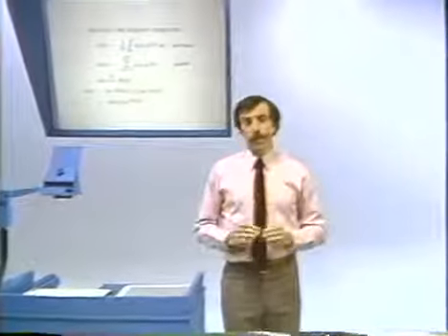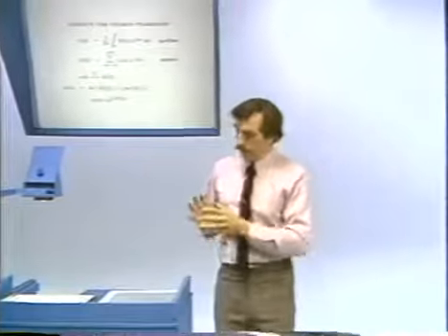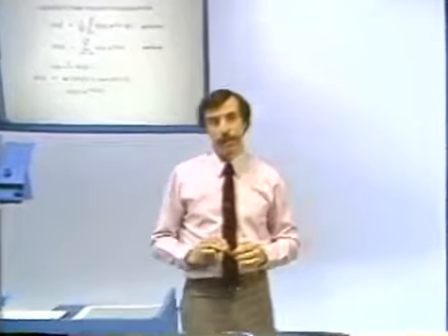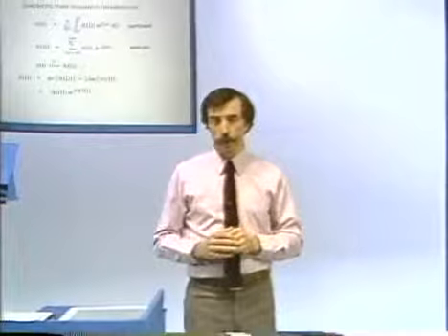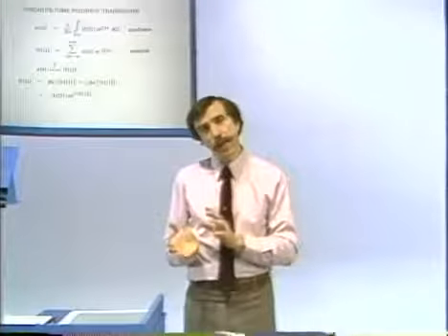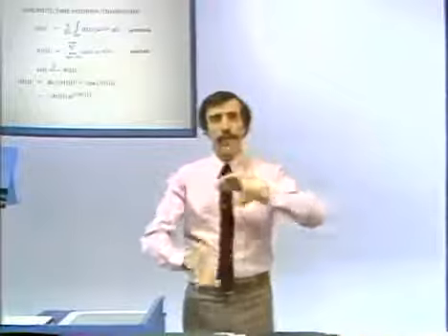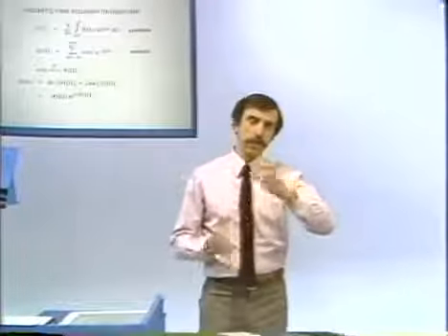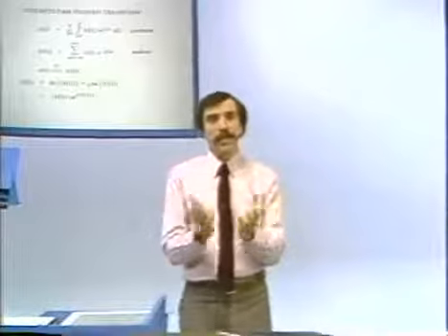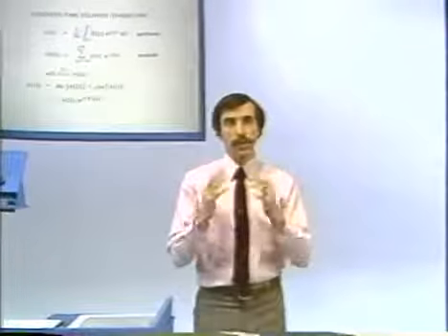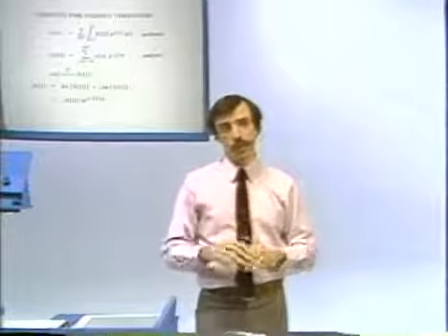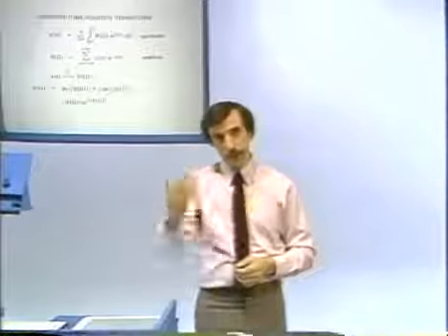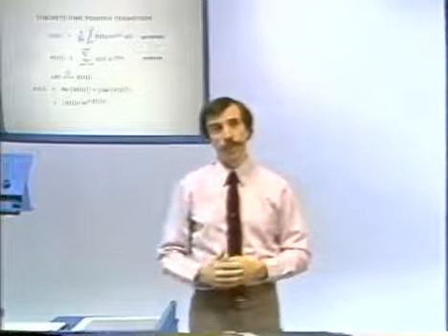There are a number of things to focus on as you look at this, and we'll talk about some of its properties in the next lecture. But one point I'd like you to think about is the fact that now there is somewhat of an imbalance, or lack of duality, between the time domain and frequency domain. x of n, which is our aperiodic signal, is, of course, discrete. Its Fourier transform, x of omega, is a function of a continuous variable. Omega is a continuous variable. That is essentially what represents the envelope.